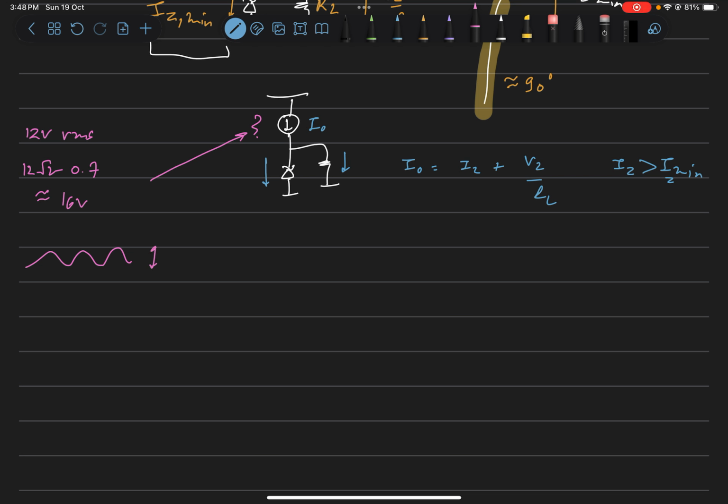And this ripple is low because we choose good enough values of R and C, and we choose a full wave rectifier instead of half wave, so that we have a decently good 16 volt battery coming from a full wave rectifier circuit. Now we give it to a resistor, and we implement this current source by this resistor as shown.